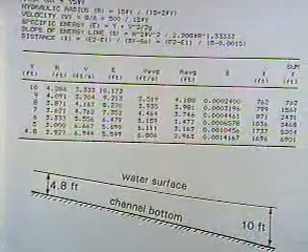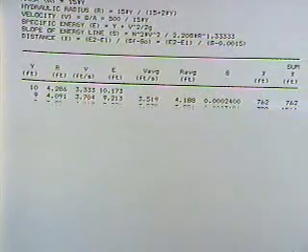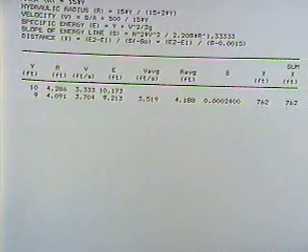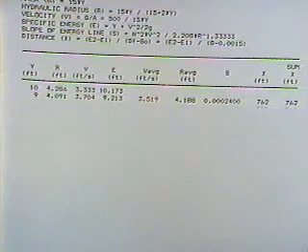And since I'm just repeating myself, I'll set up the computations in a table. Here's the table. I've listed the different depths. That's why it's called direct step, because we're just stepping through distance here. Someplace the flow depth is 10 feet, someplace upstream the flow depth is 9 feet. And you can easily compute the different values that you need to plug into the energy equation.